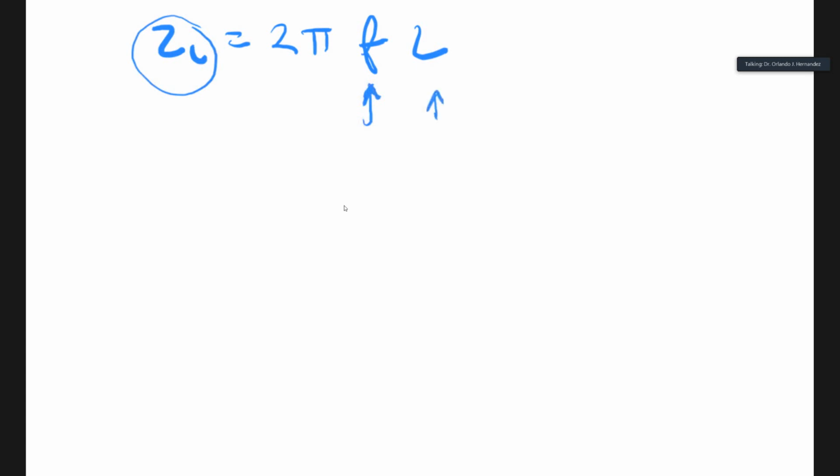So since the impedance in the steady state for an inductor is 2 pi times the frequency times L, to get any meaningful impedance, you either have to have this be very high or this be very high, which implies big. So inductors are an issue with normal sort of frequencies.